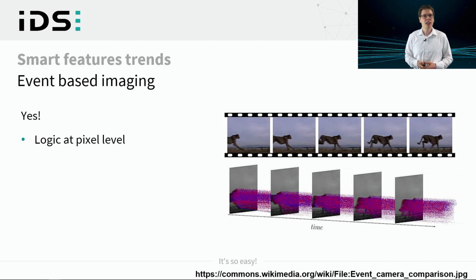A lot of logic is added for every pixel. This makes the sensitive pixel area very small and thus the size of the complete sensor huge and expensive. With chip stacking, the pixel sizes can be much smaller, as the additional logic for the brightness evaluation can be put in the stacked layer. Thus, it is more compact and affordable.